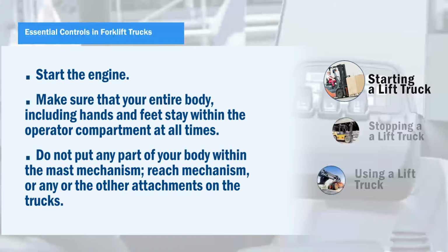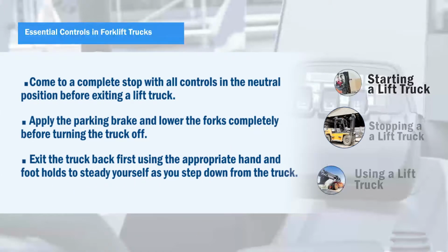Make sure that your entire body, including hands and feet, stay within the operator compartment at all times. Do not put any part of your body within the mast mechanism, reach mechanism, or any of the other attachments on the truck. Stopping a lift truck.